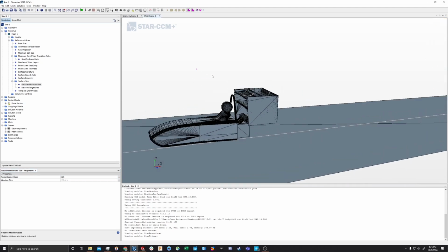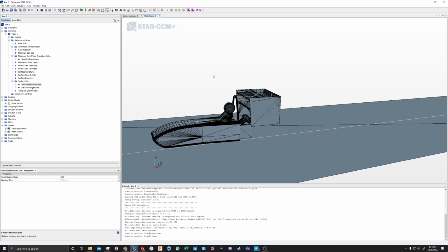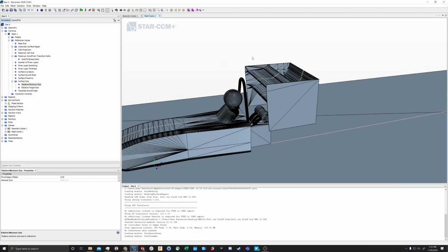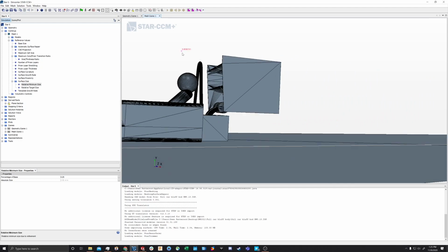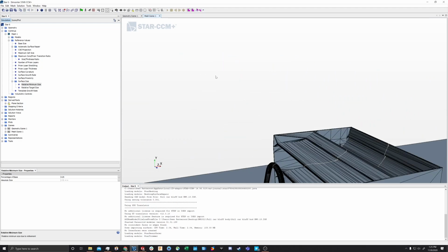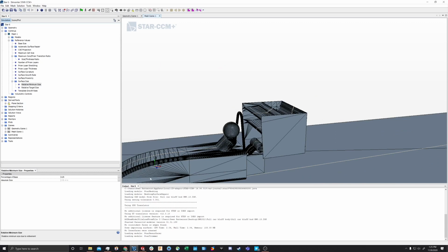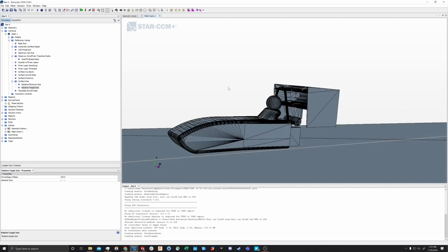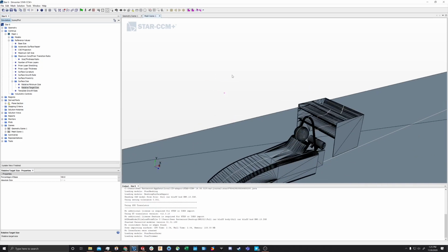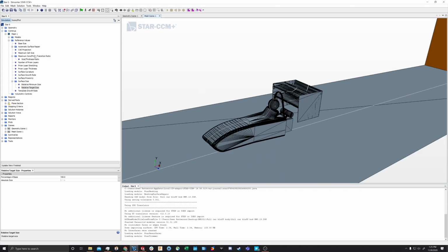But if you've got the computational ability to handle that, you get really nice refined mesh around all these round areas here, which is very good for computation, very good for simulating what we're going to see in the real world. So I like to try to keep that as small as possible, obviously within reason. If you set it super small, it's going to take a long time to compute. And then for the target size, I just leave that exactly the same. You get nice big surfaces on flatter areas where it doesn't matter quite as much.